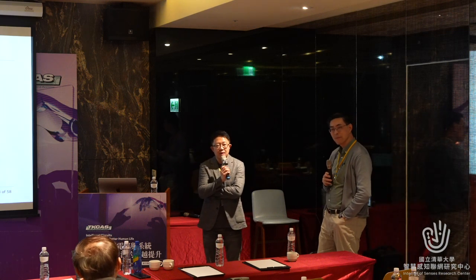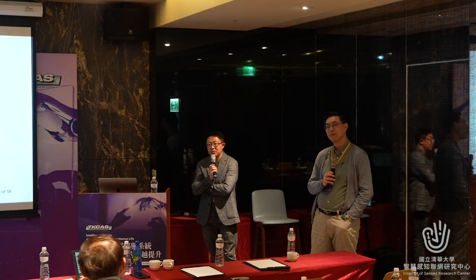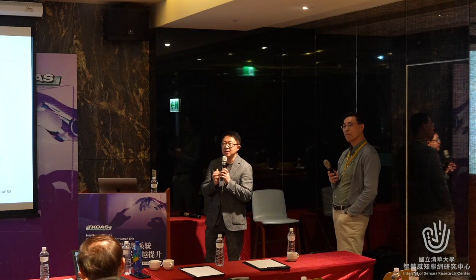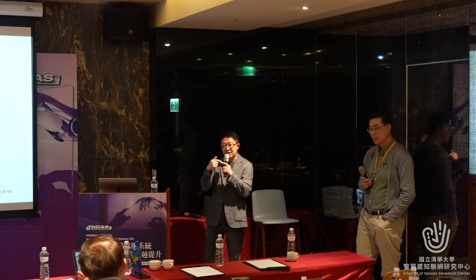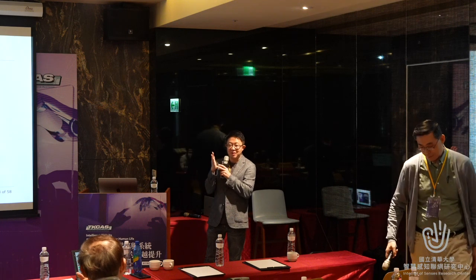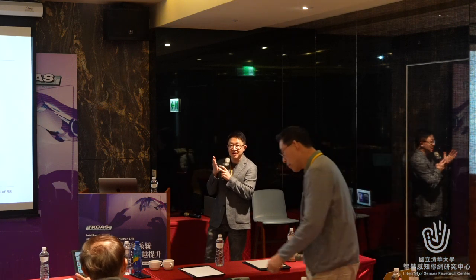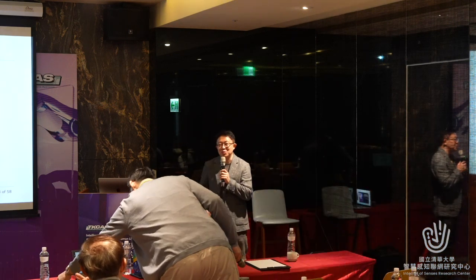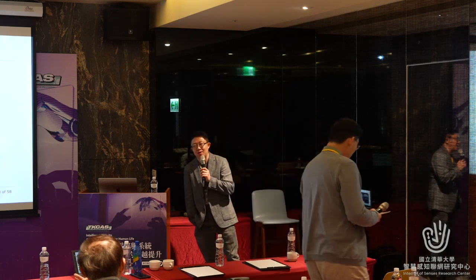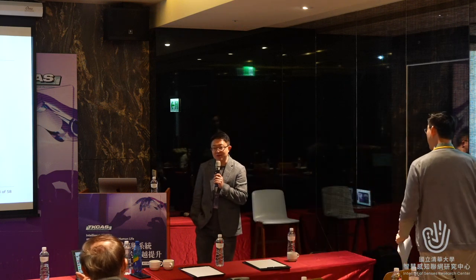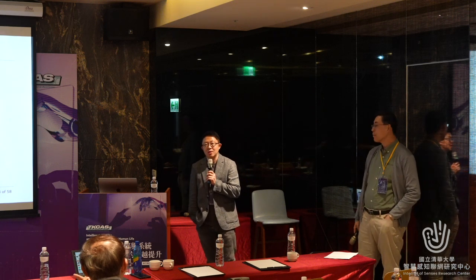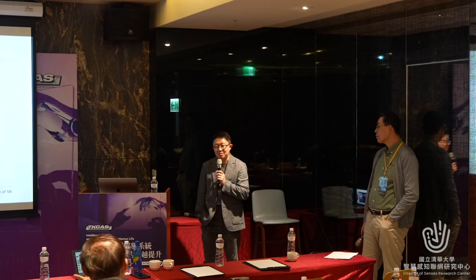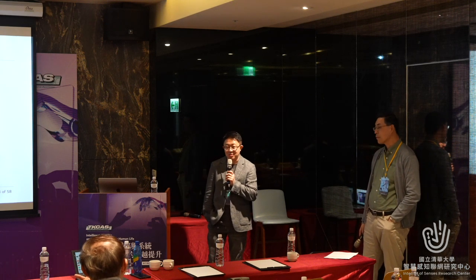Okay, so it depends on the applications, but in a usual implantable device, the electronics is kept inside the titanium can, which is about half of an adult palm size. So it is not so small, it's still okay. So after packaging, a centimeter scale chip will be okay. And in terms of the technology node, we don't need a very advanced node.